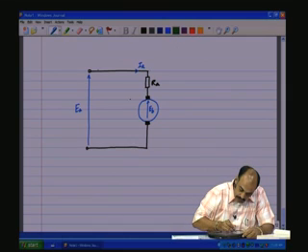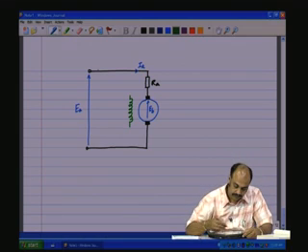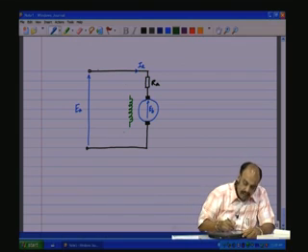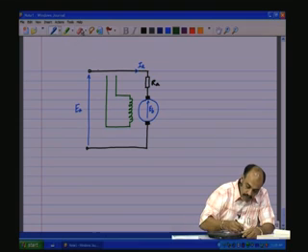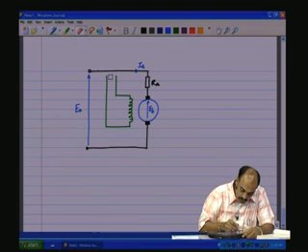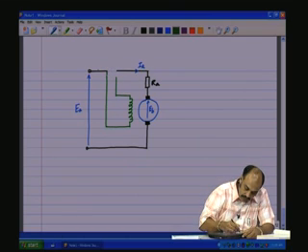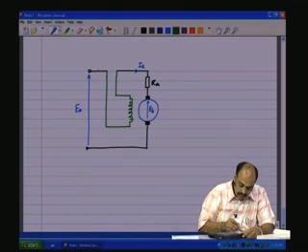There is now a field winding. Now, this field winding is not going to be connected directly across the terminals, but it is going to be brought out here and connected in series with the armature. So, what we do, we make a cut here and then connect it like that. Which means the Ia flows through the field coil to produce the flux, and also the load.